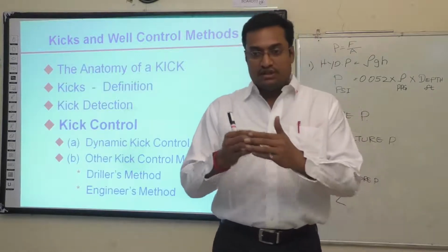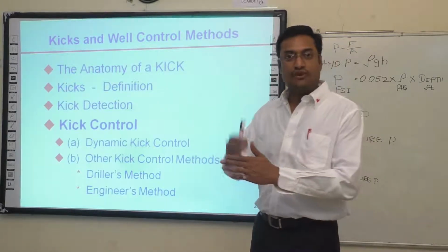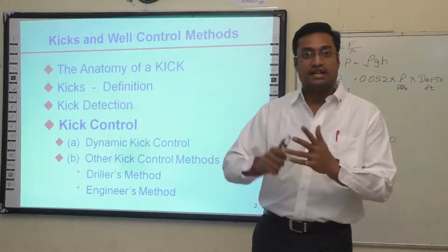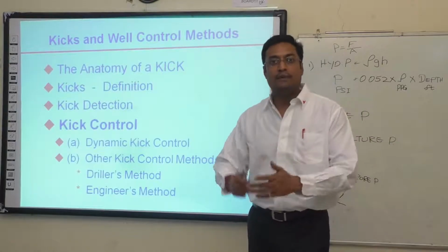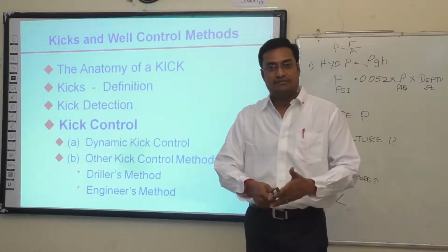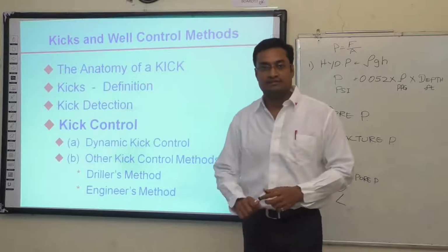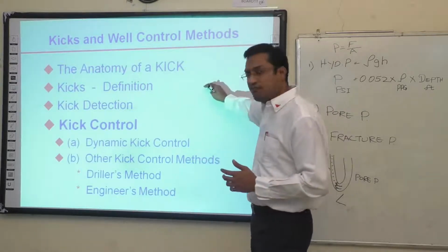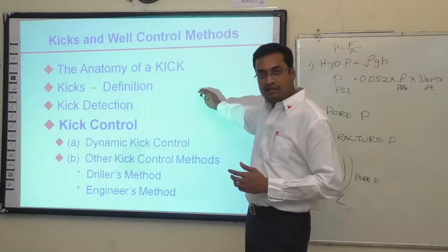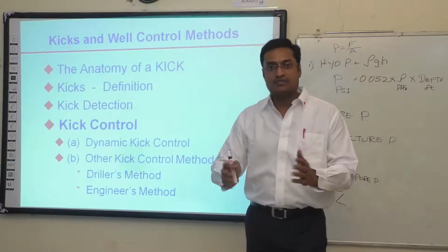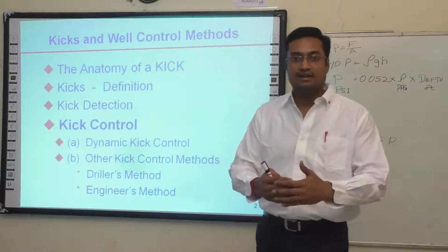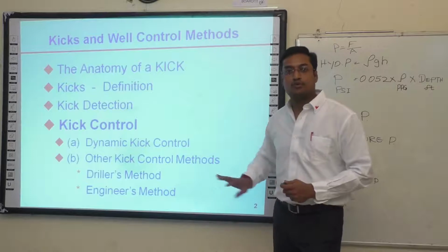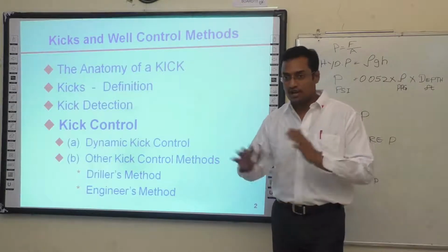Because it is not the same method which is used for every kick. Depending on the formation pressures, depending on the depth where we are, depending on the equipment we have, we decide which is the best method. So there is no trial and error here. We have to identify or detect it. Then we have to understand the situation, where we are at the moment. Then we have to select the best method and proceed with the control. There is no trial and error.